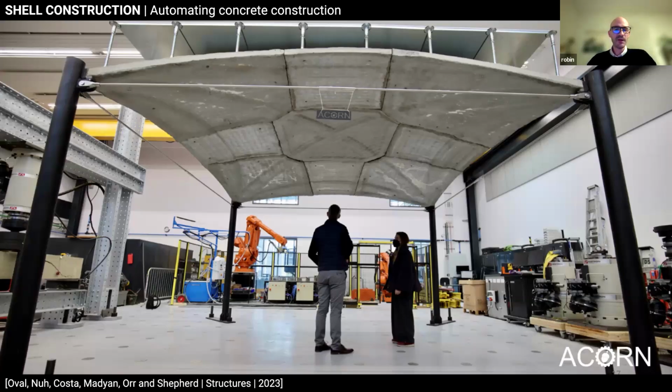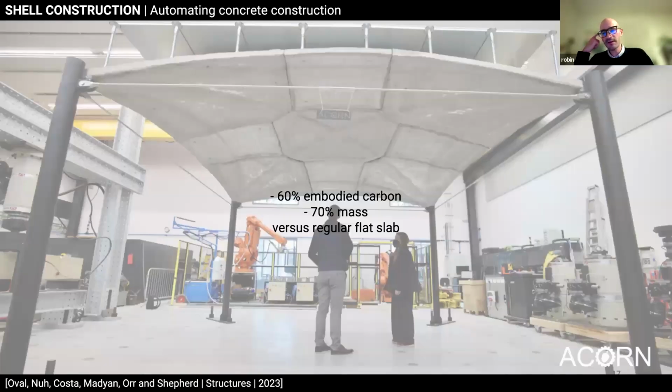carbon of the structure. And when we crunch the numbers, so if we benchmark it against a regular flat slab, which is the worst solution you could think of, you can think of worse, but that's not the best solution. We managed to reduce the embodied carbon by 60% and the mass by 70%. And the mass matters too, because eventually that's what the columns, the lower floors and foundations have to carry. So we check these two metrics mostly, but to do a more thorough life cycle analysis, we need to take into account other aspects, not just embodied carbon, but that put us on the right track. So we're quite happy with it.